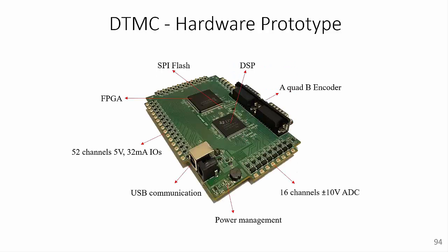And this is the controller board that's used to drive the matrix converter hardware. It has a TI DSP on board, and this DSP is directly programmed from Workbench. The Workbench model-based design allows you to program this DSP without having to know anything about the device, nor having to do any C programming. This board also has an FPGA on board, simply to convert the gate signals. Since the DSP cannot drive 24 gate signals, we have an FPGA to convert the duty cycles to drive 24 gate signals. And we have an onboard encoder to measure the speed and ADCs to measure the currents and the voltages.